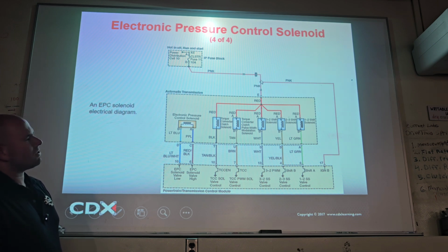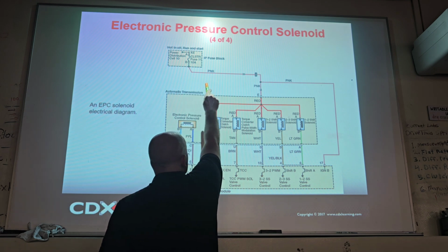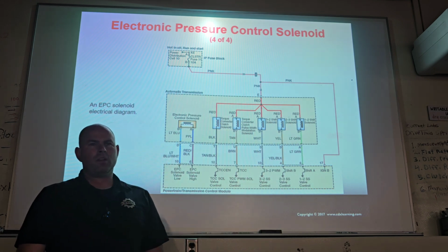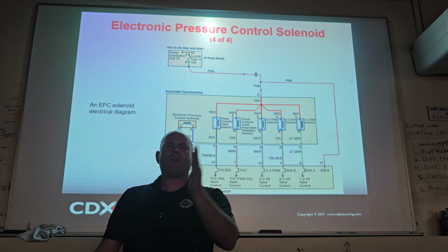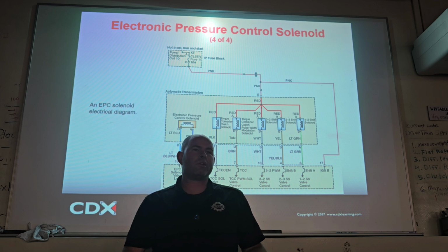And here you can see, in this case, this is a 10 amp fuse. Now do you guys understand what I was saying about that Jeep? If that 10 amp fuse blew, all these would be what? Off, off, off, off, off, off, off. So what's the default for all off? I don't know, third, fourth, something like that. Make sense? They always build it so that if you lose power, it's drivable.